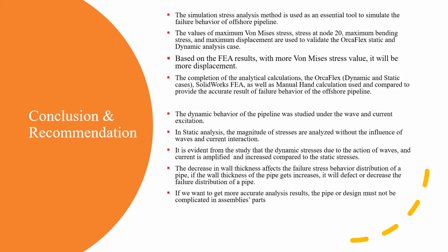Simulation software such as SolidWorks FEA 2021 and OrcaFlex 11.1 dynamic analysis is used to calculate categories such as the maximum von Mises stress, stress at node 20, maximum bending stress, and maximum displacement on different axes on different nodes. So we learn that when we have more forces, we have more von Mises stress, as well as more displacement.